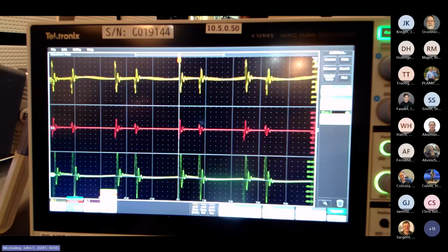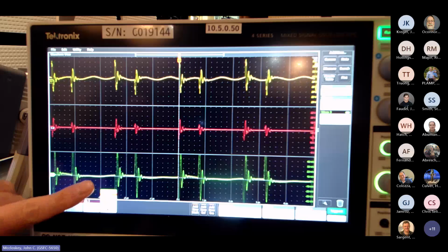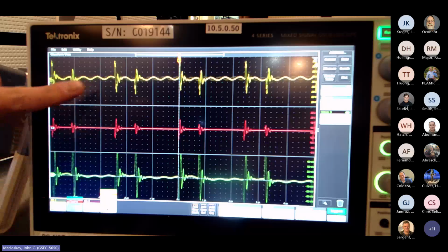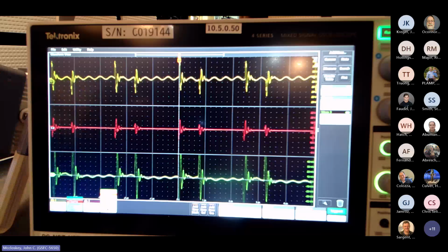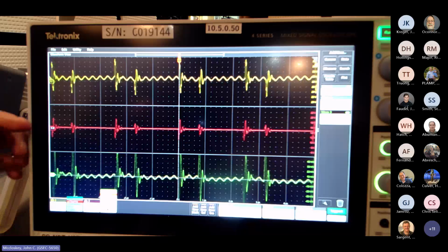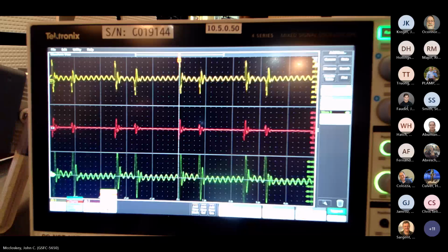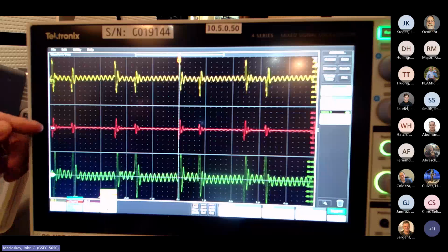At the low frequencies, the impedance is high enough that you're not getting much current. Now we're at about 600 kilohertz. All right, you're definitely starting to see some of the current ripple getting in on our current probe. And it's clearly the same frequency, right? That is our injected frequency. No mistaking it. But the output is actually still holding pretty stable. Now there's some ripple coming up on the output.